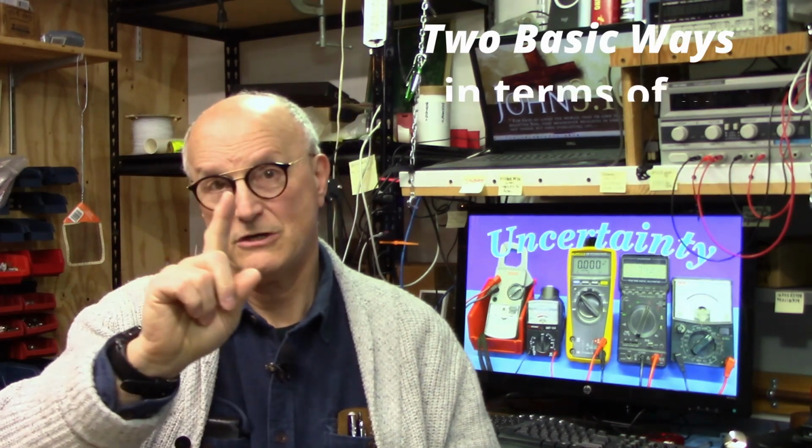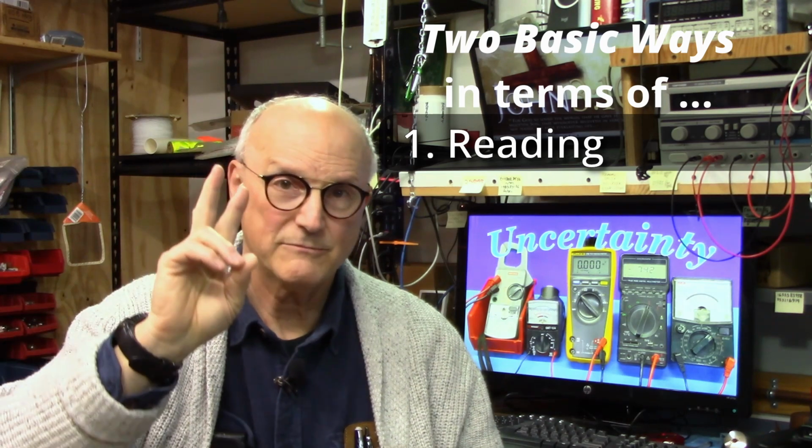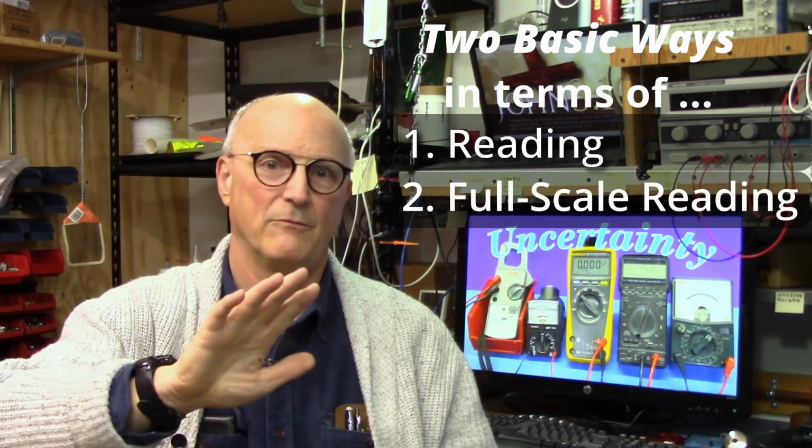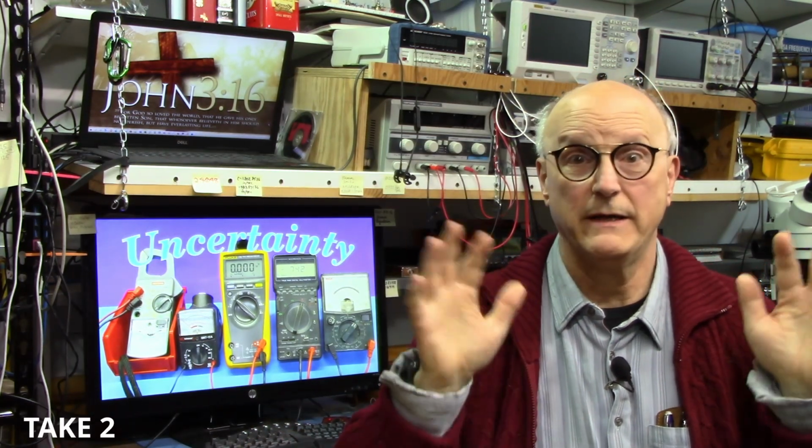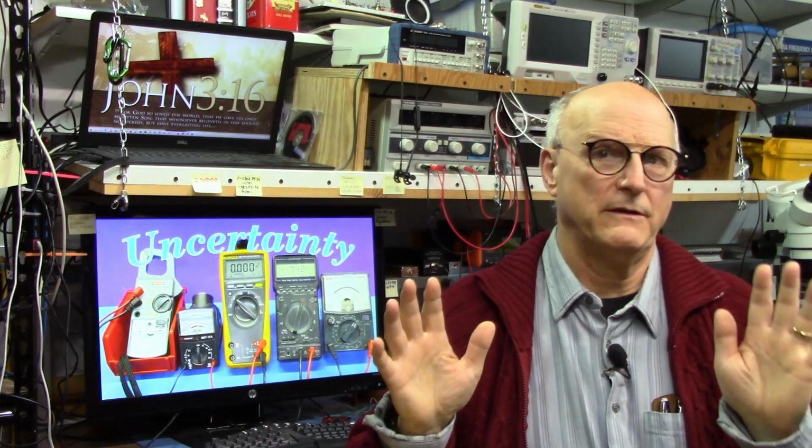Now, every measurement device has a specification for accuracy, and this specification can be stated in many different ways. And two of the more basic ways that this is stated are in terms of its reading and in terms of the full scale reading. Now, most often these terms will be in percent, so let's try to understand these just a little bit more. Well, the first one is the easiest to understand. After parsing through the mind-numbing specification sheet on my Siglent oscilloscope, I find that it is a plus or minus 3% device, assuming that the human reading the screen is done perfectly.